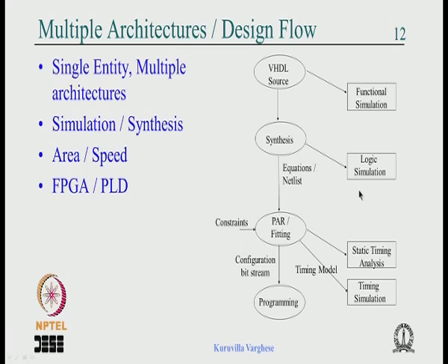Now if you have an AND gate and you give the input at 100 nanoseconds, you will see the output coming after some delay. Maybe it will come after, say, 102 nanoseconds, depending on the delays incurred within the FPGA. But for a complex circuit this is very time consuming, because you have a detailed model of the wires, switches and the various blocks within the device. So a timing simulation which takes a long time is quite cumbersome.